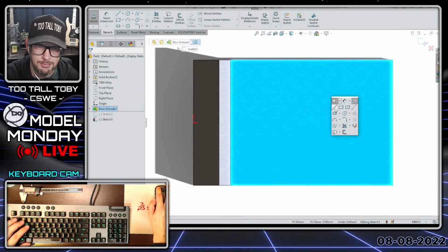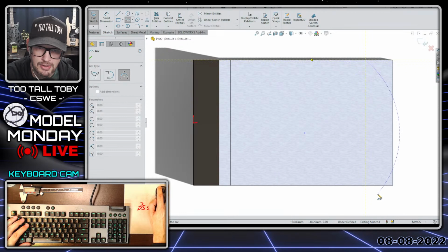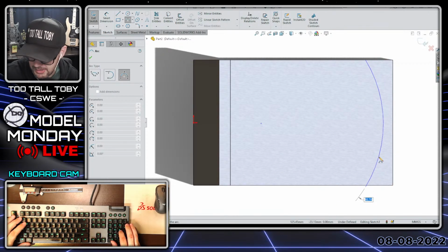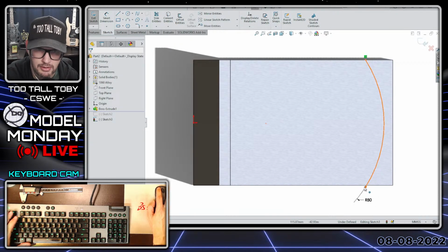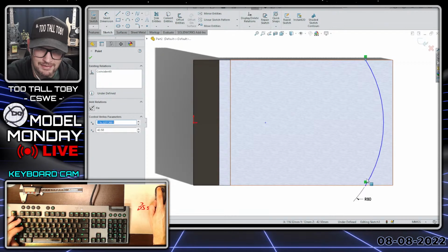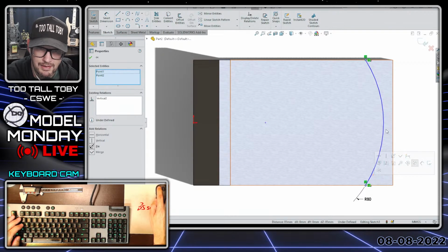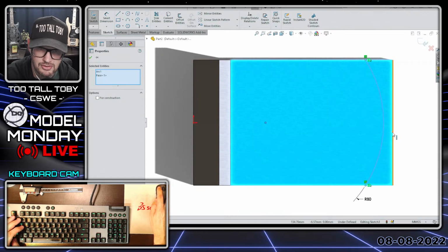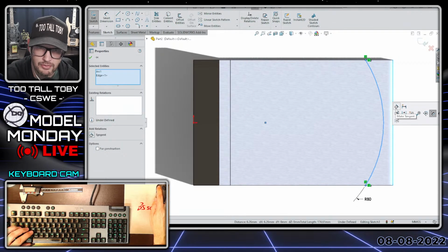Begin this, pick this face, begin a sketch, orient the view, and I'm going to create my 3-point arc here. And again, right in this command, I can just type in the radius, even though I'm doing a 3-point arc. And also, even though I missed this point here, so coincident, and then I'll take this guy and make this vertical. And then I'll take this guy and make this tangent. And that should give me the correct location for that arc.